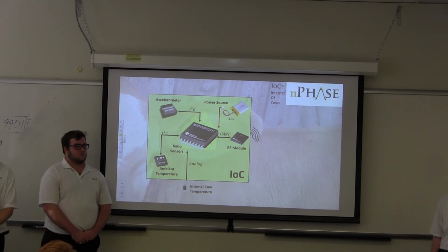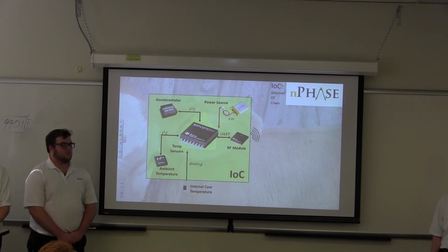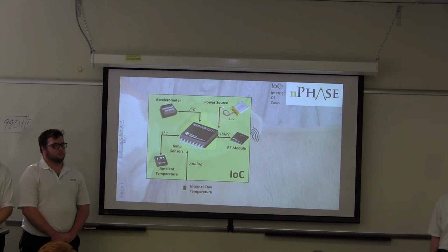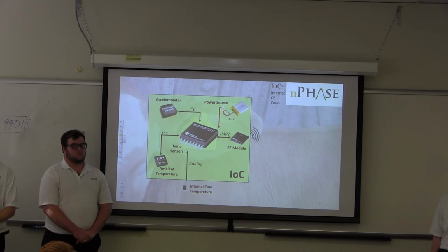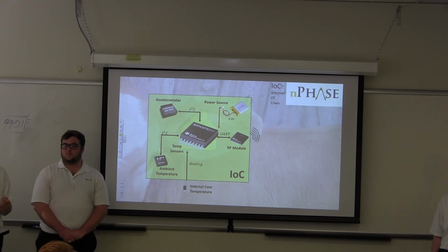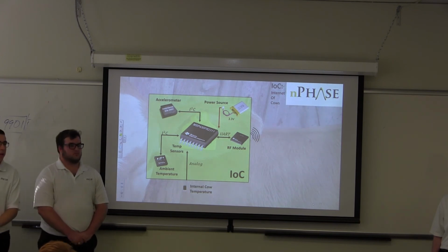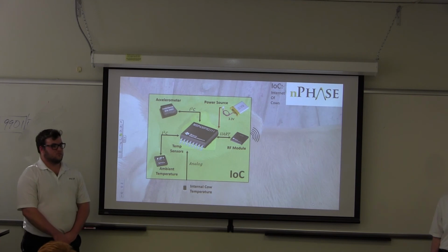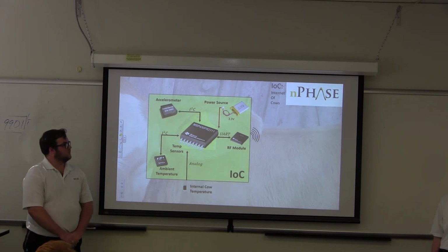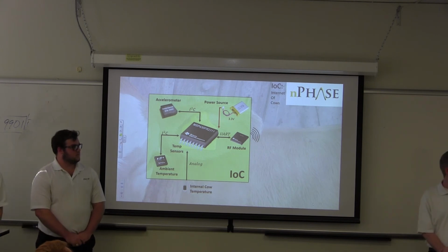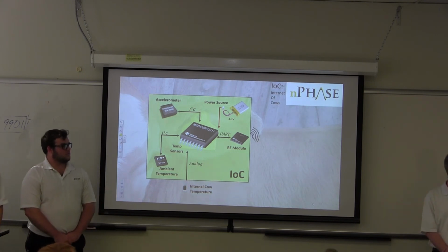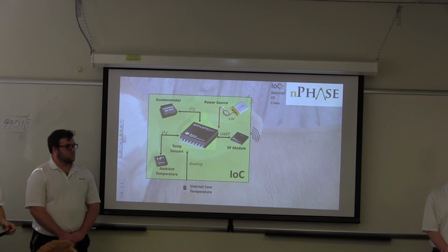Is the consumer or your sponsor expected to recharge this battery and then be able to replace other ones? Yes, they should. It's just a Phoenix connector, so they can just unplug it, charge it however they need, and plug it back in. And the capacity of the battery? It's 850 milliamp hours. And I have a whole power budget that I've been making, and it's everything in the data sheets divided by, we actually have a little bit over a month. So that meets our requirement for power.